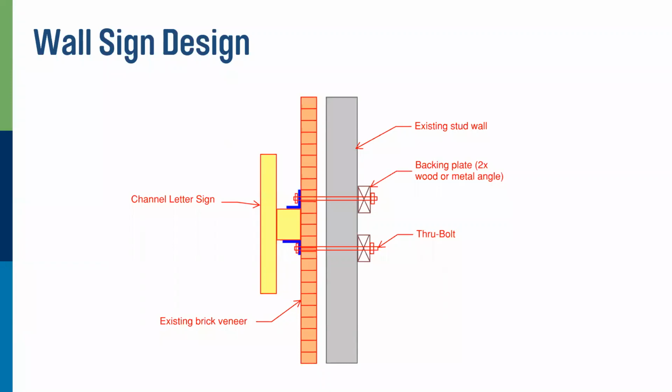Plus, the 3/8 inch is a lot more durable versus 1/4 inch. It doesn't rust as much. So that's the other thing for all your fasteners. All your fasteners have to be non-corrosive, meaning they have to be either stainless steel or galvanized, or some sort of protective coating. There's a lot of epoxy coatings and things nowadays, so you can possibly do that, but most of the time you're going to get either stainless steel or hot dip galvanized. And again, that's just so that the bolt doesn't rust out.